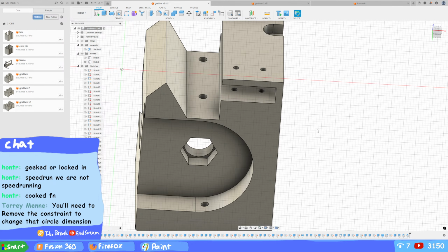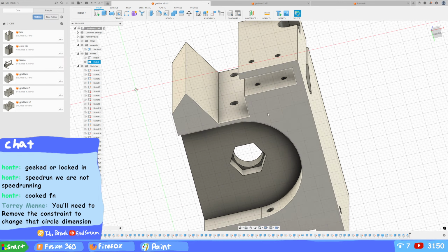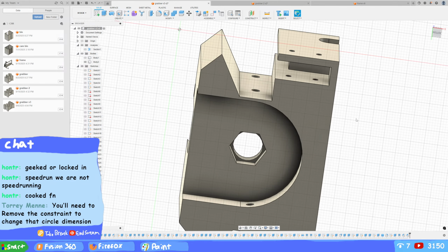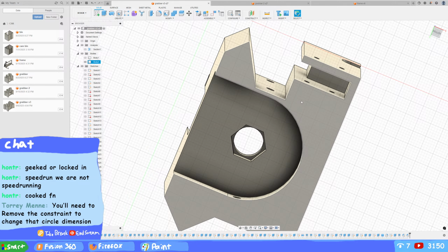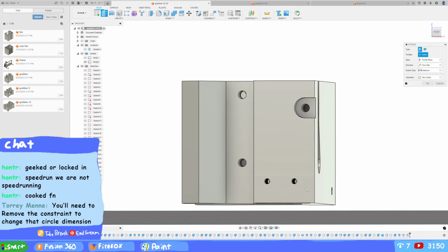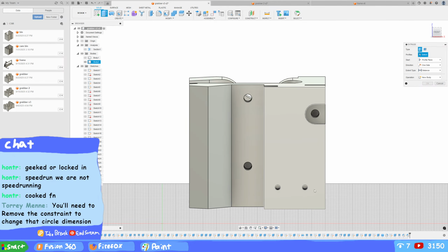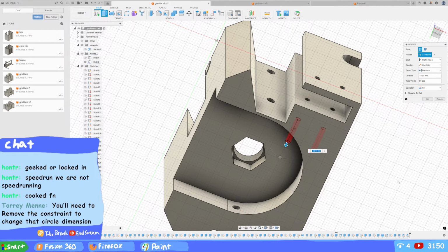I need to fix this. So what's something I can do? I can rotate it 90 degrees and just jam it next to that, or I can add a little air gap where I can slide a knife through and just wiggle it out. That's always an option. Or you know what else I could do? I can take these and extrude them in more.